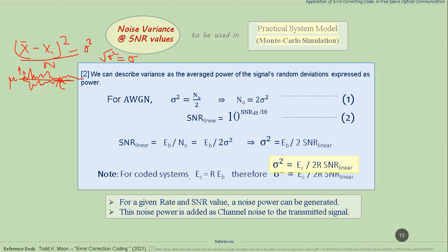But here we are looking at voltage squared, which is proportional to power, and that is why variance and power are the same. So this is the average noise power in a sense, and the spectral density of white noise gives us the average power.